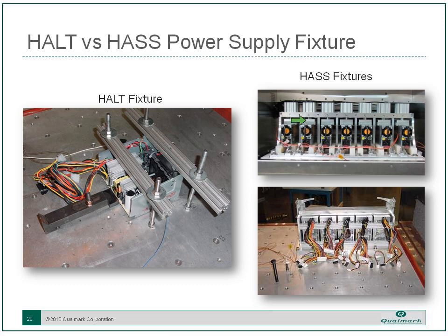And here you see, remember the power supplies that we saw being tested earlier laying flat on the table, and we were testing 4 at a time on the table. Now we're in a HASS configuration with those supplies. We've changed the orientation. We actually have pneumatic clamps that are clamping down on the individual products, so the entire clamping process is automated to ensure consistent clamping pressures. Once the fixture validation has determined what those clamping pressures need to be in order to get uniform vibration across the units themselves.